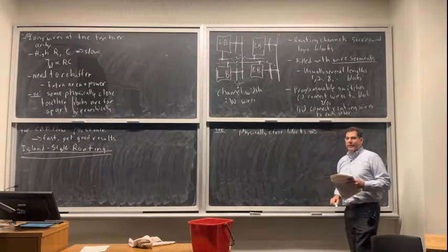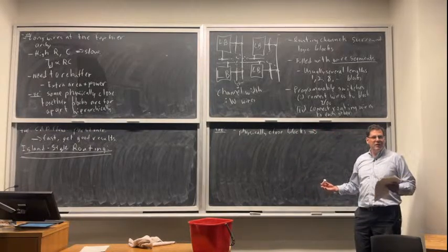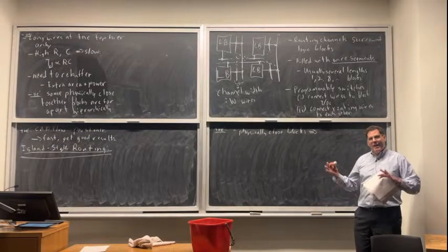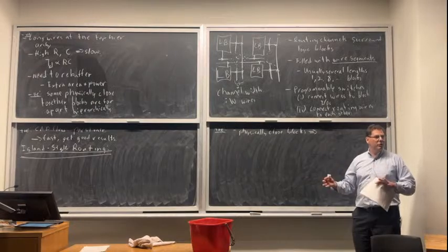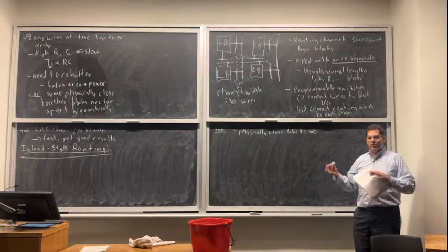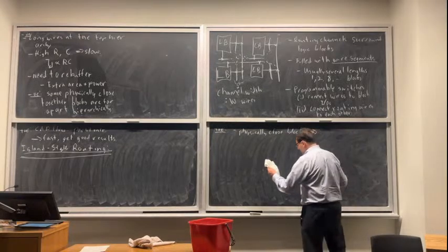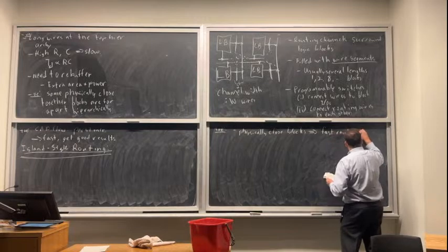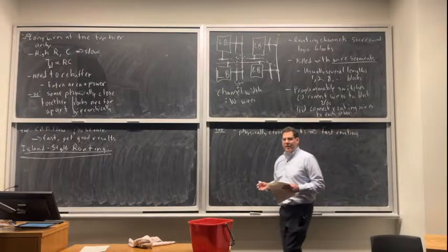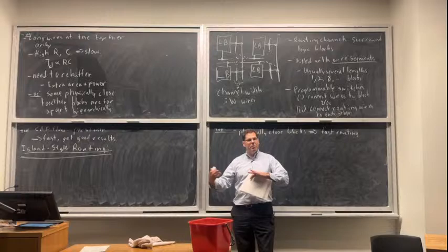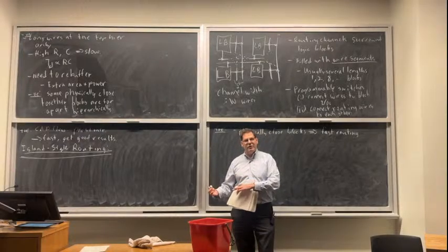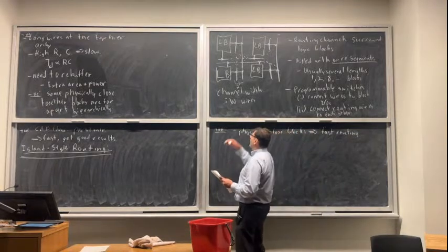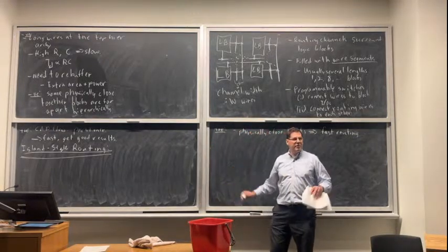We have fast routing. Now we can connect them with short wires, or if they're not quite so short, maybe a medium length wire. But if you're close, we can build some options where you won't use much metal. And your capacitance will be lower, your speed will be higher, your power will be lower. So we can get fast routing. Whereas in the hierarchical FPGA, this was only true for some blocks that were close together. If they're physically close together and they were near each other in the hierarchy, then you got fast routing. Here, if you're physically close together, there'll always be some fast routing choices.